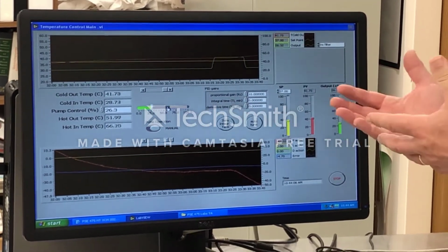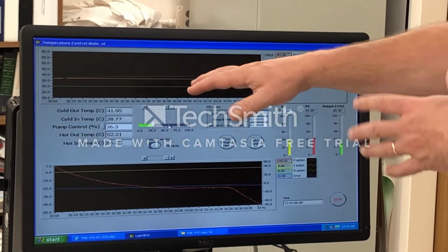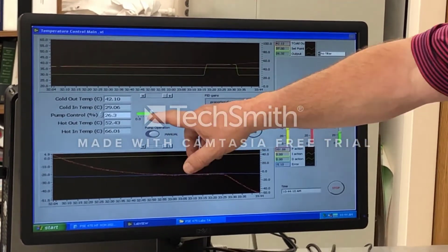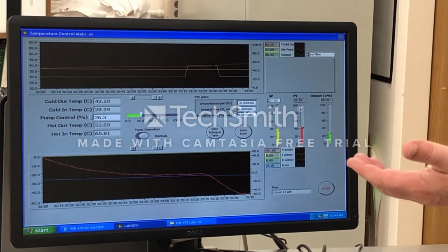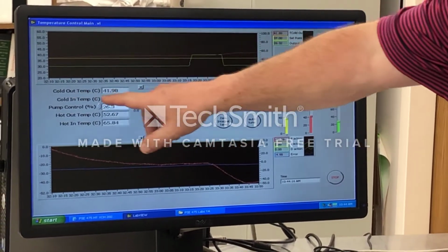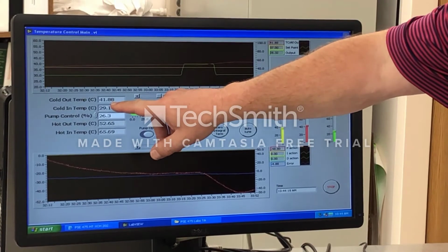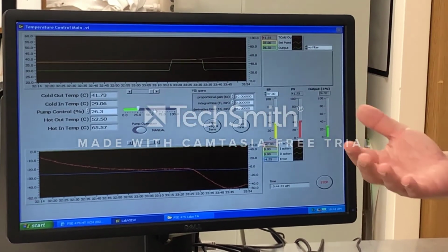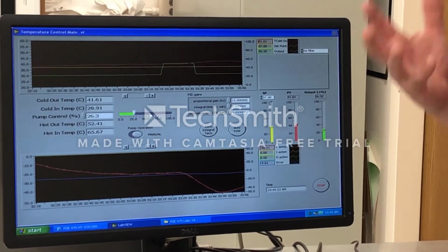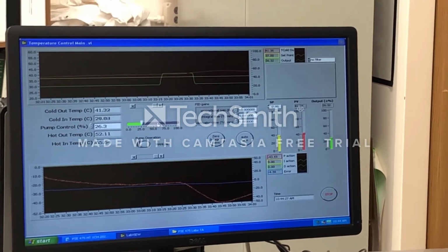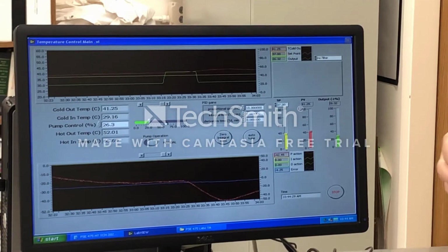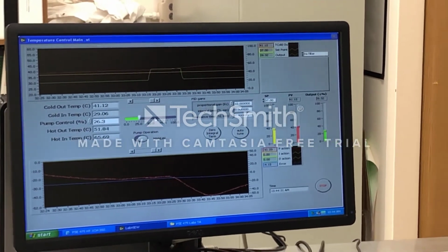What we can do from here is get the system in steady state and then make a bump change in the pump speed. And then we will watch the cold water out temperature as a function of time. That's called an open loop bump test. And typically we will collect all the data, and then we will fit that to a first order plus dead time system, if it is actually a first order plus dead time system.